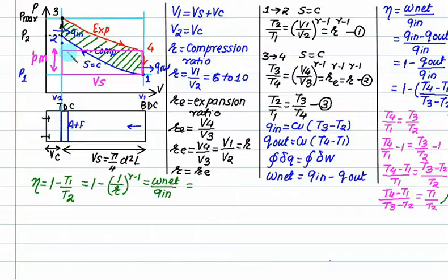So you have to equate this area, which is a rectangle of area Pm multiplied by Vs, with the actual W net, and then we can solve for Pm, which is called the indicated mean effective pressure, a hypothetical pressure assumed to be constant over the entire stroke.